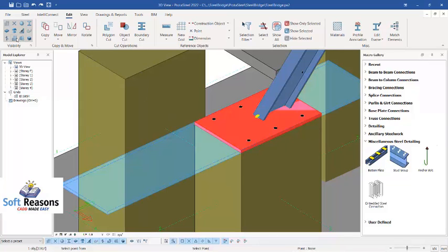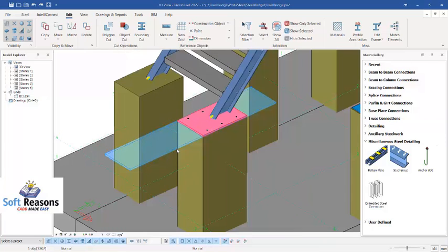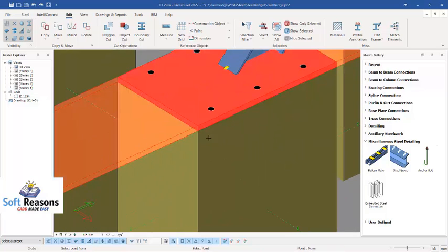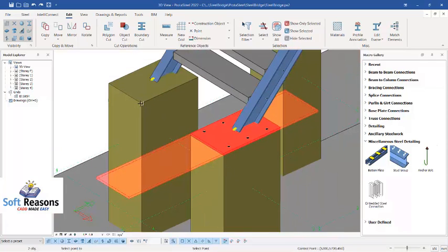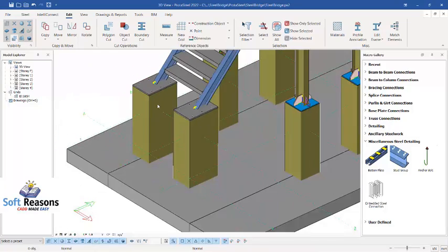But before then, I have to activate these macros, the cut auxiliary macros, after which I will get everything selected, both the cut auxiliary macros and the plate right there, just like this. And then I use the by 2 points option. I pick the topmost edge of this plate, just like this, all the way to this point, and place it right there. So you can see what is happening. If I deactivate these cut macros, you see, we still have it just like this.